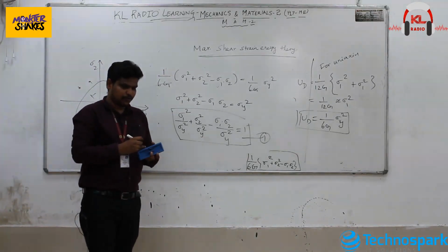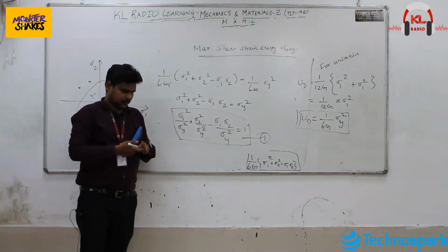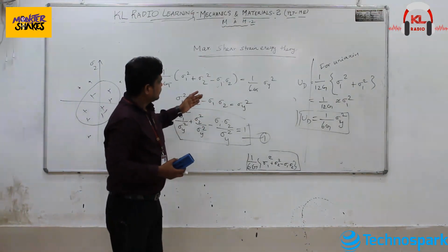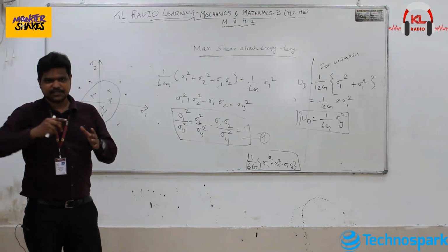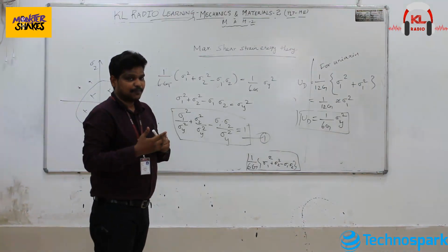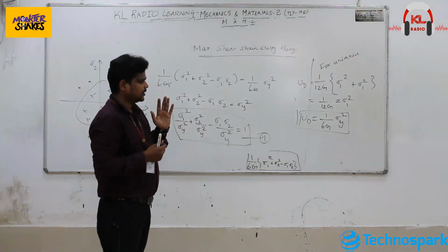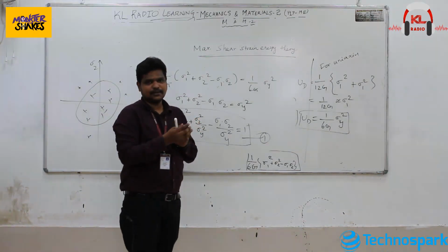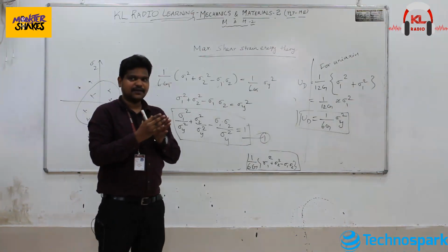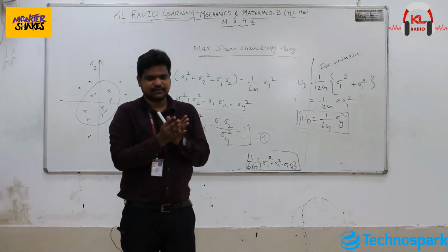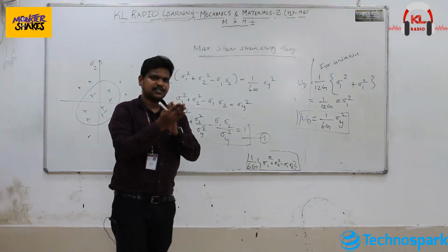Right. So again I will explain why this theory alone is so important. As I said before, when it compares with the maximum strain energy theory, the maximum strain energy theory compares the total strain energy for the failure criteria. But from experiment we know very well that the material fails only at yielding. Before that it will undergo only a volumetric strain, or it just reacts as if the load is acting as a hydrostatic loading. So there will not be any distortion.